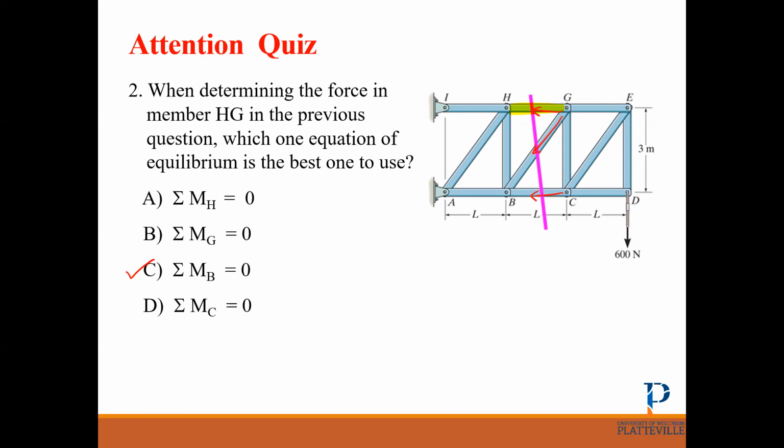Remember, we have all these internal forces. If we take the moment about point B, these forces cannot make any moment. The only force I need to find is this one, and it's easy to solve.